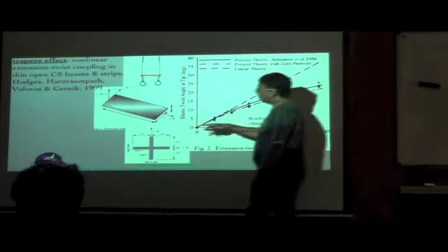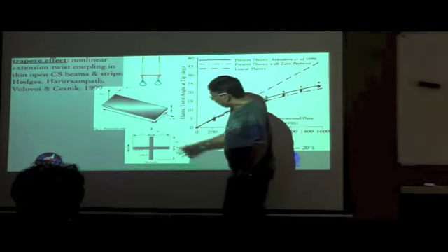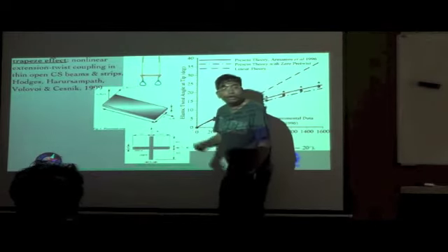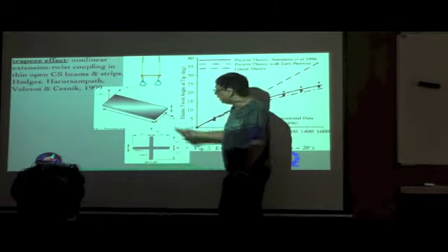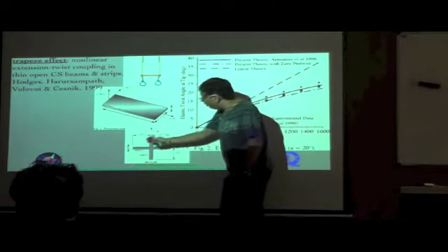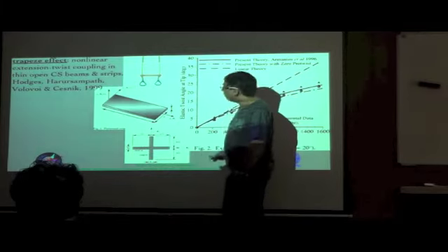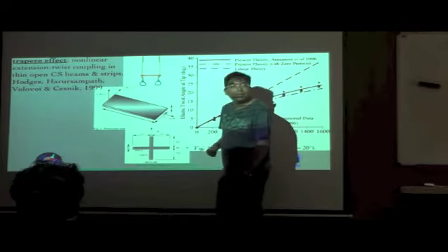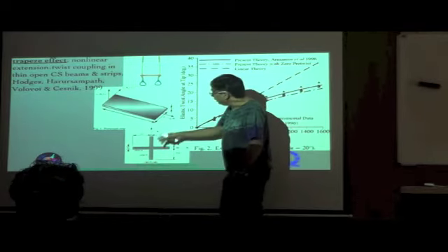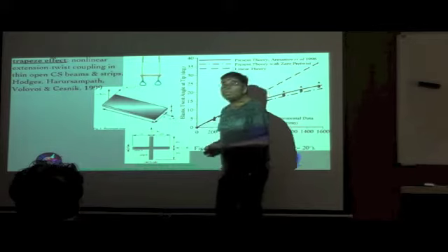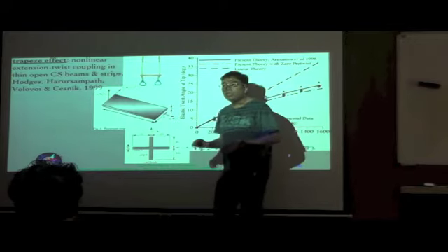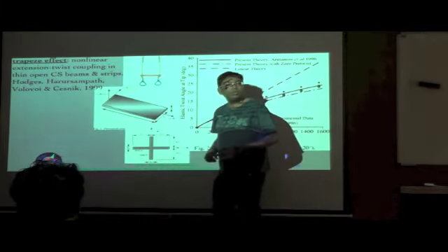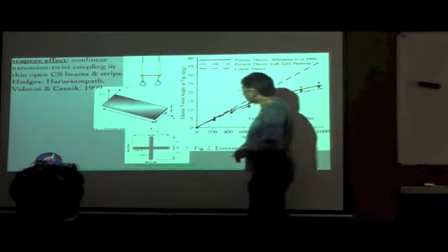So here's a typical such thin rectangular strip, and another cross section which is like a cruciform. Again, an I section or Z section, hat section, all of these channels will qualify under this category. And in all these cases, whether it's an open cross section or a thin rectangular strip, it's very easy to see that the torsional stiffness is very low, because of which even with small values of torque, you're going to have large twists, okay, twists per unit length.